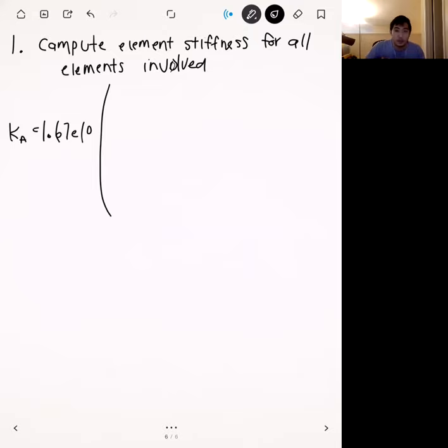Okay. And so this is going to be 12, 12, okay? And then we have 6 times L. And so 6 times L here is 6 times 3, which is going to be 18. Okay. Then we have a minus 12. Then we have a 6 times L, which is going to be 18 as well. Okay. And so that's the first column of our element stiffness matrix.